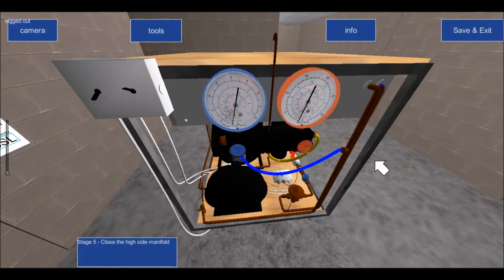And because you're being asked to describe the control system that we see in front of us, then I'm asking you to describe the pump down cycle. But you are correct. There are 2 different ways. So yes, the room stat will either make or break the feed to the compressor, and that's the on-off cycle. Or the room stat will make or break the feed to the solenoid, and that's the pump down cycle.